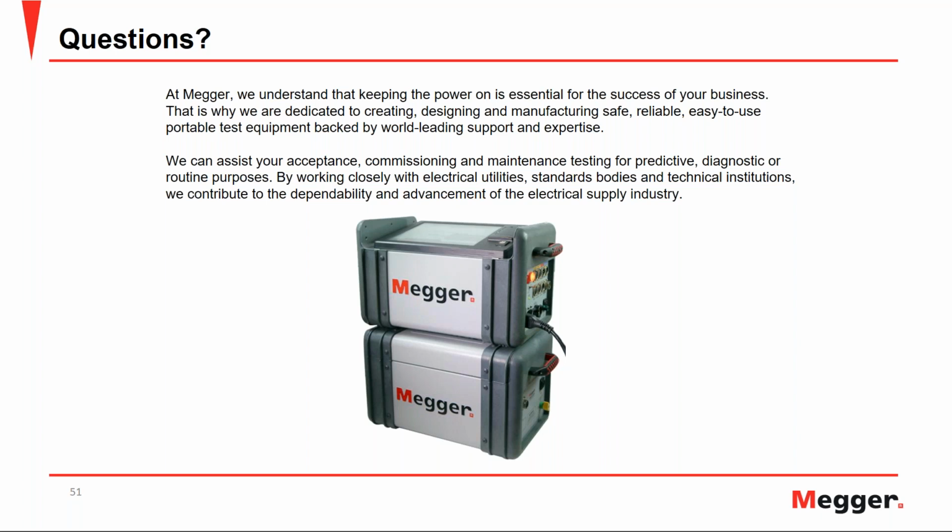So when you perform power factor measurement, obviously you not only get the power factor values, you also get the capacitance, leakage current, and watts loss. So when you are evaluating your results, you not only look at the power factor, you look at the other parameters as well. Typically, when you talk about capacitance, anytime there is a mechanical change in the insulation condition, if something has got compressed or shifted, it would lead to a change in the capacitance value.